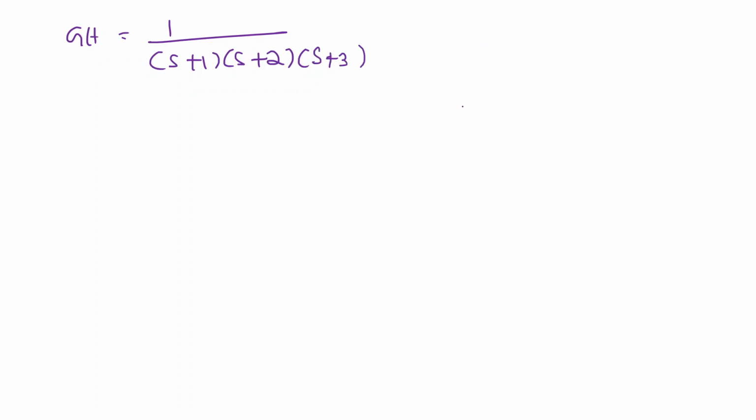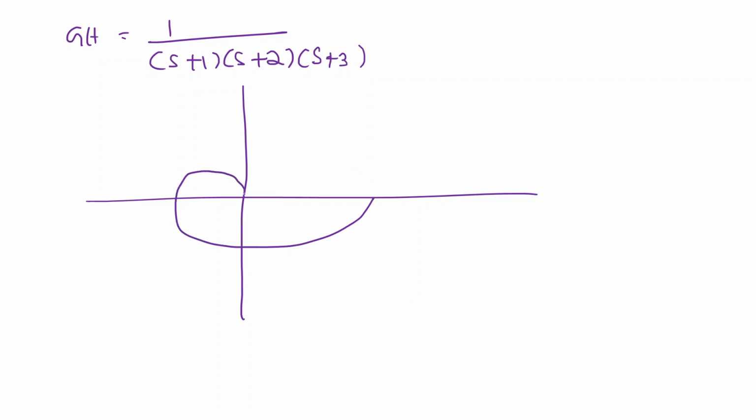Now you tell me, sir, for this you have already drawn the polar plot. Yes, sir. Minus 180, it will go like this, right? This is the polar plot. No, no, sir. This is the minus 270, 360. You have to start at omega equal to 0. This would be k by 6, right? Now I'm taking this as a k value. I'm just putting k, okay, sir? Because I want to solve this question: for what value of k is the system stable?